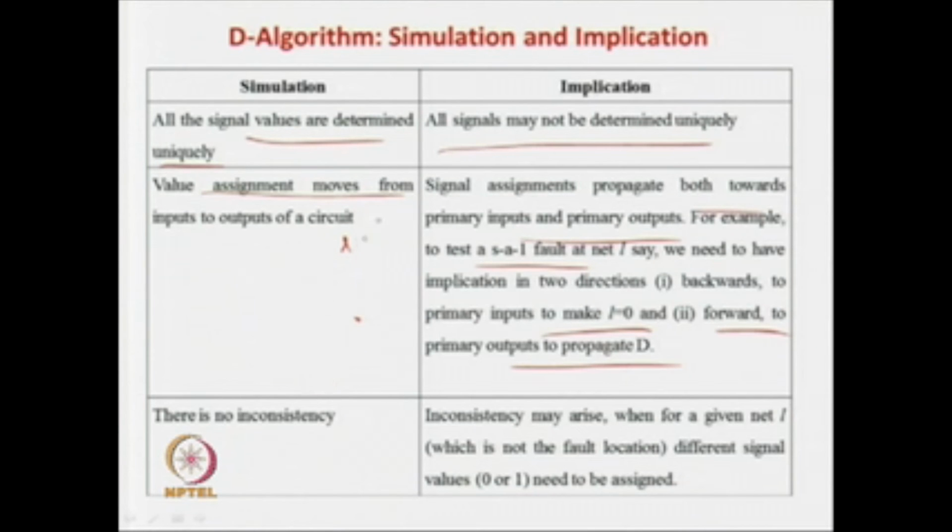So, this was talking about the AND gate. In the AND gate this is stuck at 1, so you need a 0 over here. The normal case is 0, the fault case is 1, so this is D prime. We know the value of the output to be D prime, and both the inputs are x, so the output should be 0. You can have x 0 or 0 x, any one of them is fine.